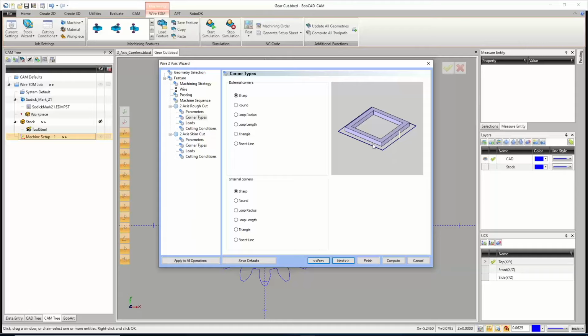Like in this case, the part is a sharp corner, and so do we use a more abrupt movement where we go with a 90-degree turn? It really depends on the geometry, but like that picture shows there, that's a 90-degree turn, and depending on feeds and speeds, could be a little bit of a tension builder right there. So there are some options to go in and round the corners so you're not doing that 90-degree sharp turn.